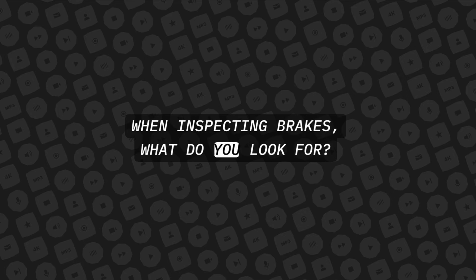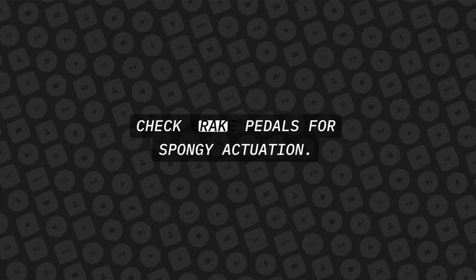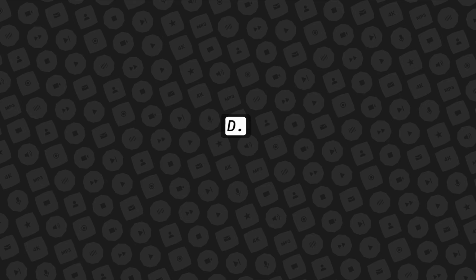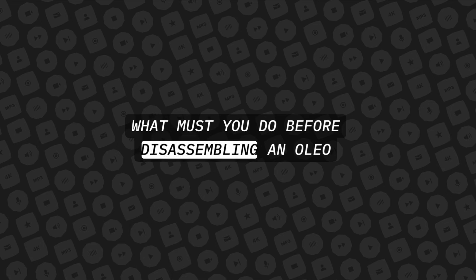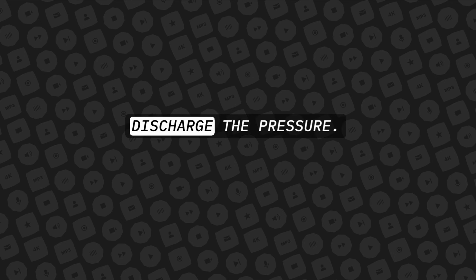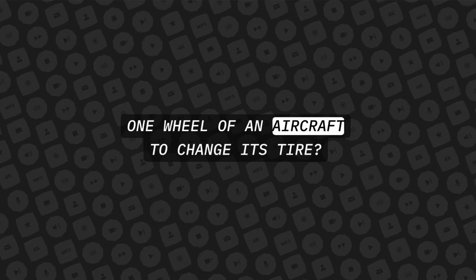When inspecting brakes, what do you look for? A. Check for leaks while the system is pressurized. B. Check flex hoses for swelling, cracking, or soft spots. C. Check brake pedals for spongy actuation. D. Check brake pedals for excessive travel. What must you do before disassembling an oleo strut? Discharge the pressure.